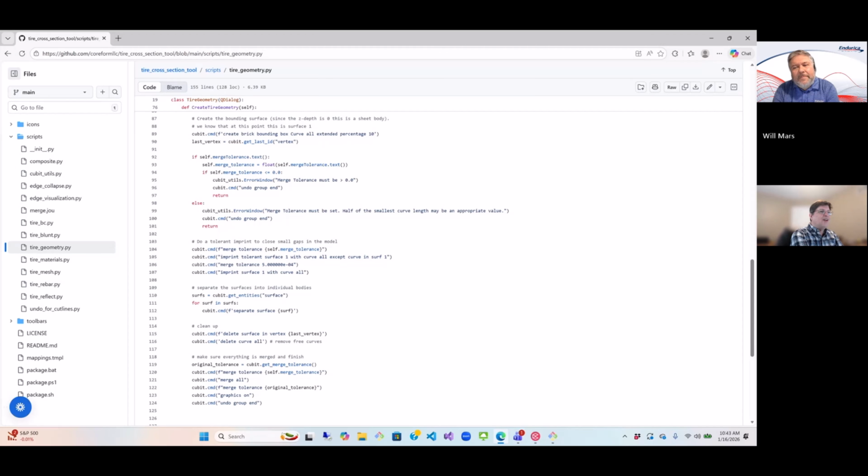The biggest issue I've found with trying to create treads is cleaning up the geometry and doing it in a way that you can create the minimal set of hexahedra. Everybody always wants coarse hexes, and the coarser the mesh, actually the harder it is to generate. Cubit uses a process of subdivision. If you're doing hex meshes, you've got to cut things up. Cubit's got some pretty good tools for cutting things up. I'd love to see those improved a little bit more for tires. I have done tire treads with Cubit.